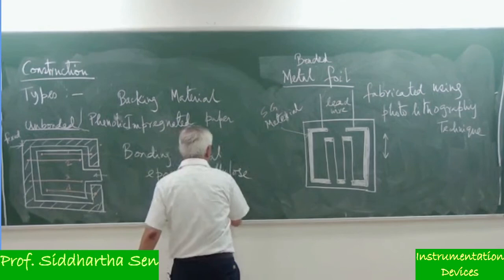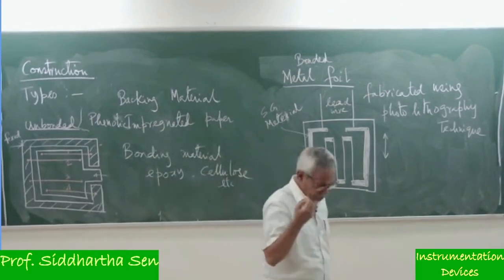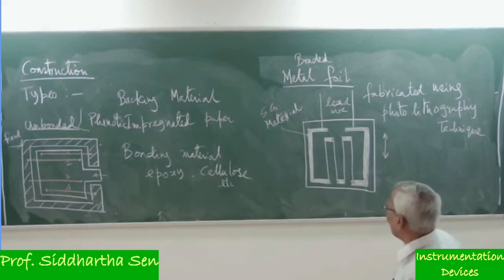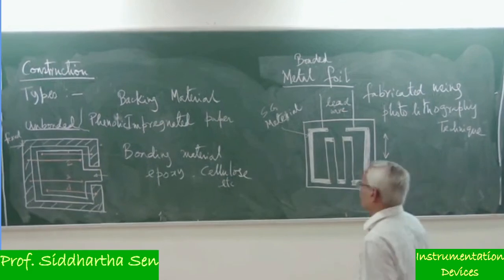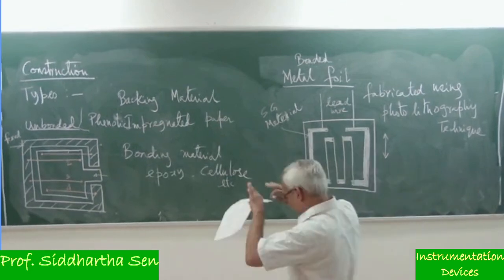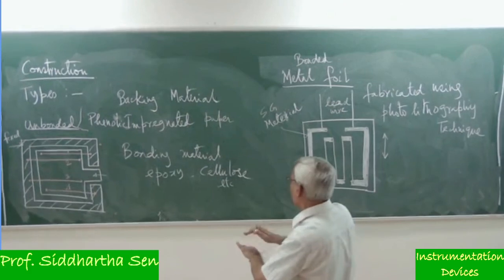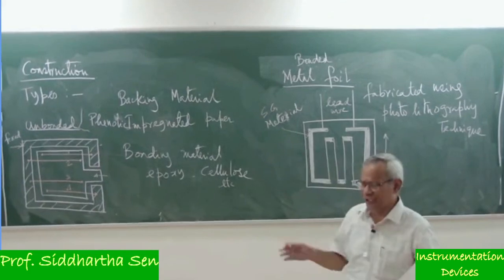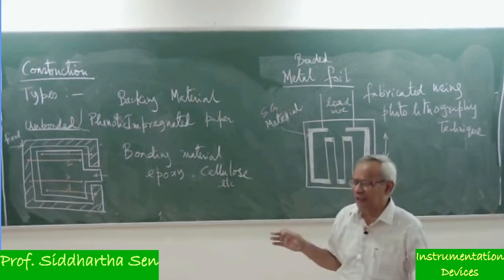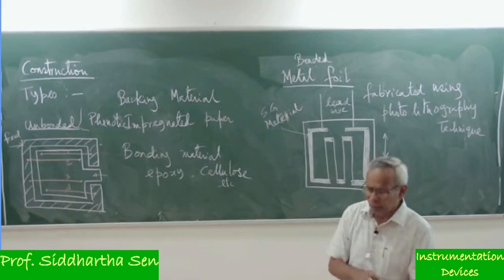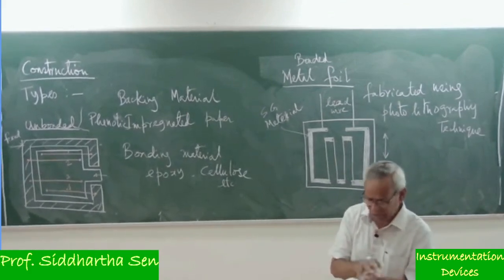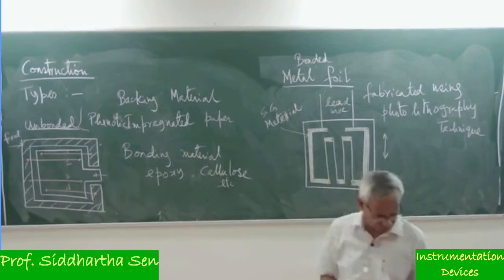But definitely it has to be looked into, and we need to note down that the fabrication or the bonding has to be done carefully. Otherwise, even if your structure, strain gauge circuit or everything is fine, if the strain gauge is not bonded properly over the structure, that will cause the problem.